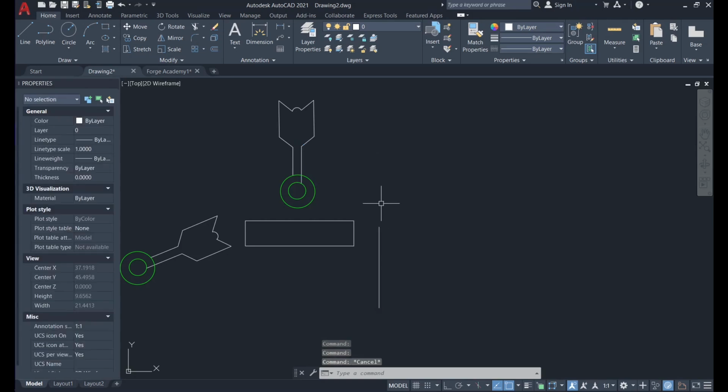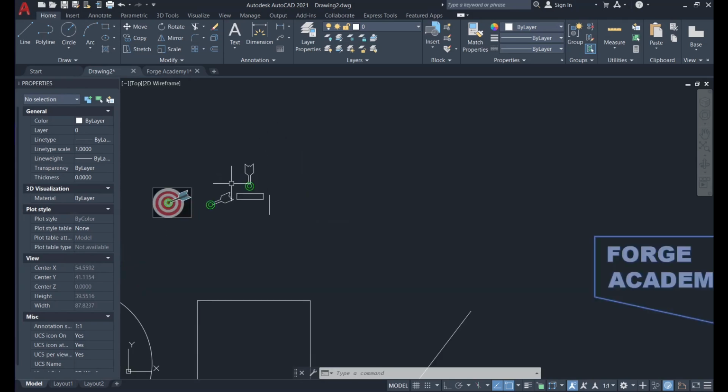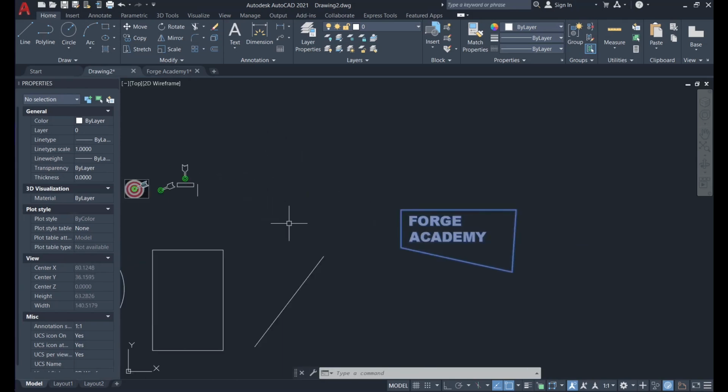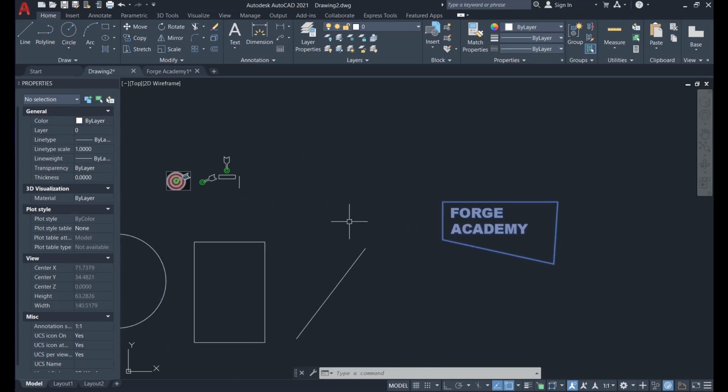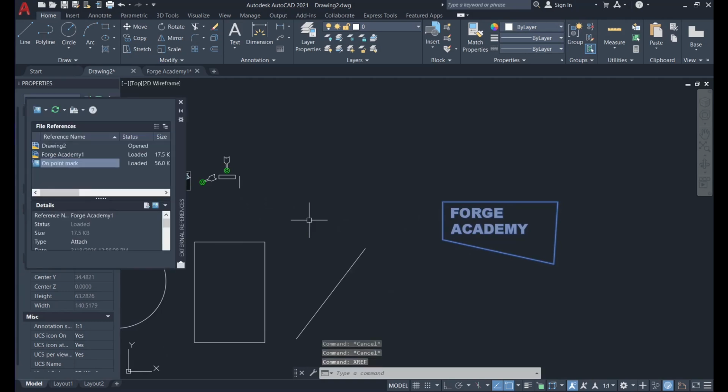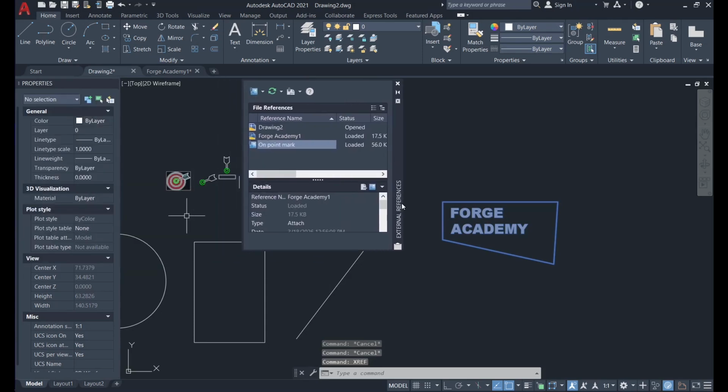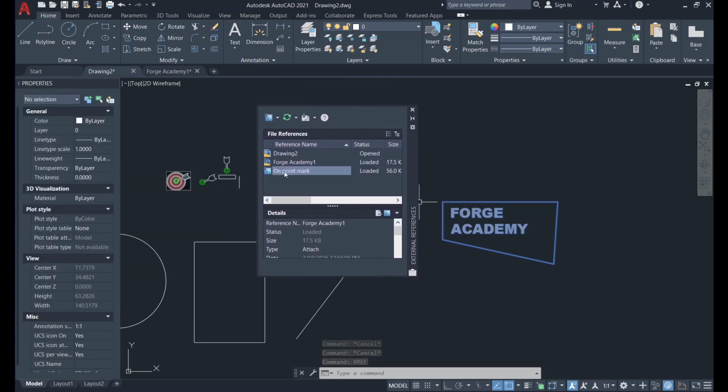So this is how you use reference from scale command, also reference from rotate command. Now you know that you can copy the base point externally and also use the reference command, the external reference. Also, you can remove the references in the same window by using the right click.